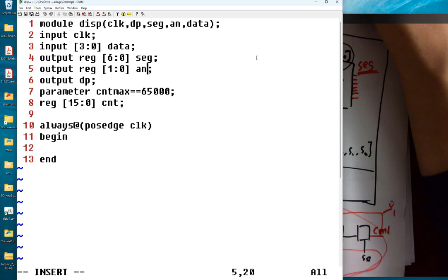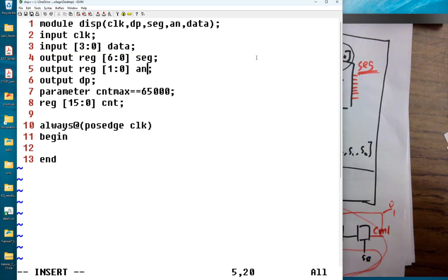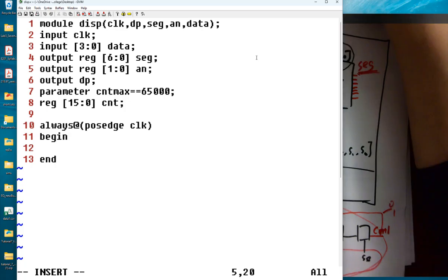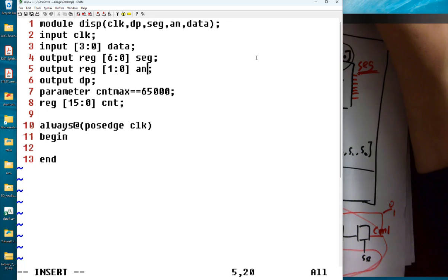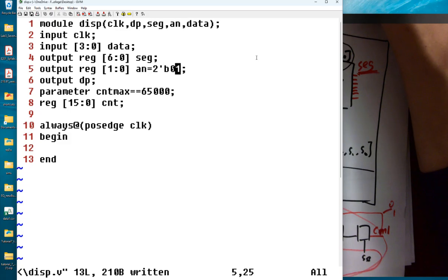It starts with, to display a number instead of displaying a sign, right? So AN, you can choose to start with something. It's not starting with all zeros, right? You need to give an initial value. So only one is on, one is off. In that case, we can assign an initial value to it. If we do a 2-bit number, let's do 0, 1, for example. It doesn't matter because you are always flipping these 2 digits.